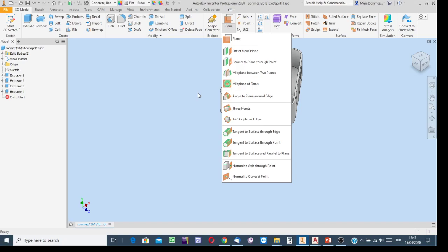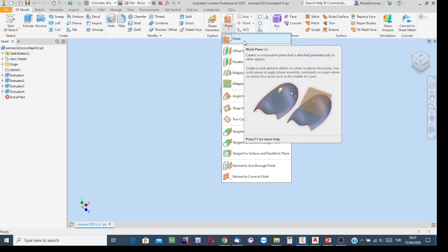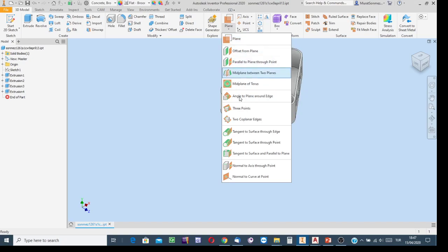For instance, have such a paper and then take a sketch right on it. Well, if we use this tool, then the created work plane, that imaginary plane, will be unlimited. Well, remember, the first time I introduced that facility of the software was when talking about oblique surfaces, in Inventor, how an oblique surface can be created. For the first time, under that question, I talked about the work plane facility.